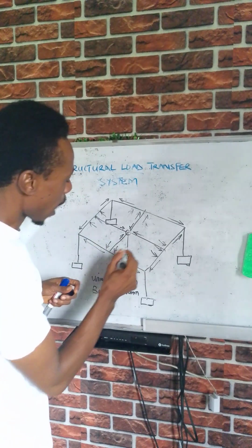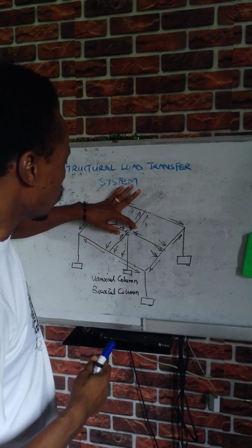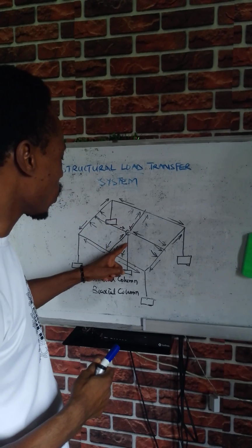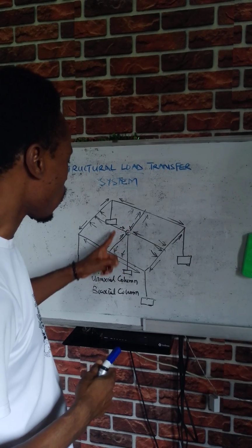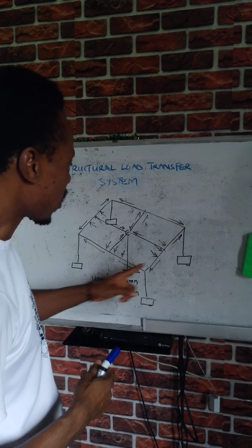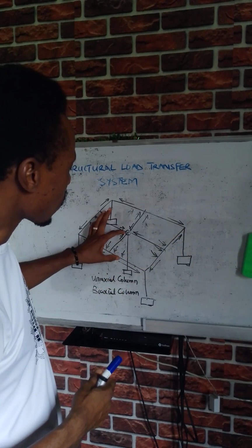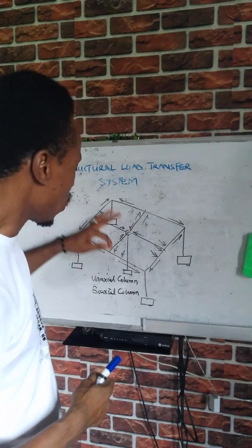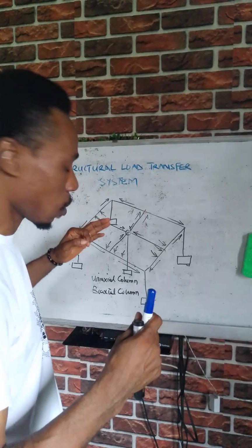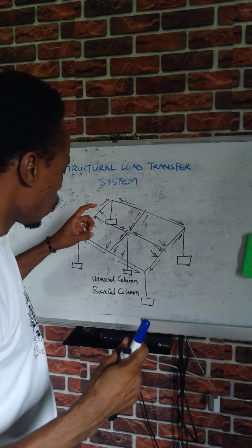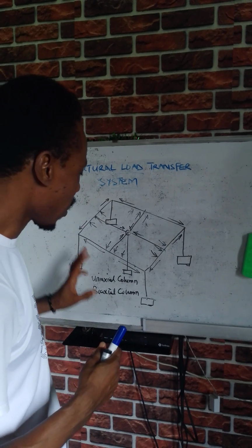So they are being hinged to this column. So this load from the four directions comes into this column. So you see that this column supports load from four side beams. It's quite different from the one that is supported by two side beams. So when you have intermediate columns, especially the beam conditions will tell you if that column is a uniaxial column or a biaxial column.